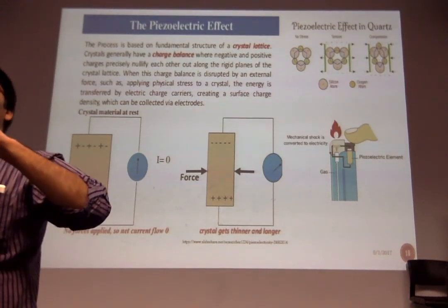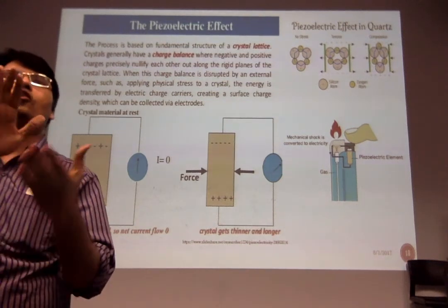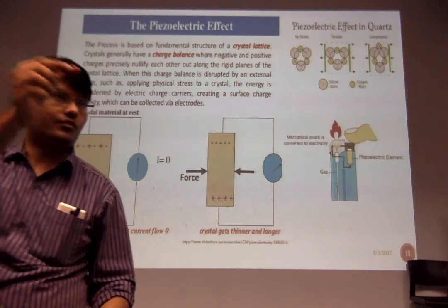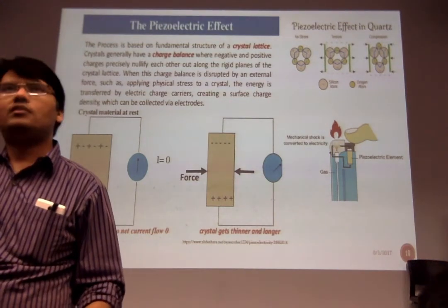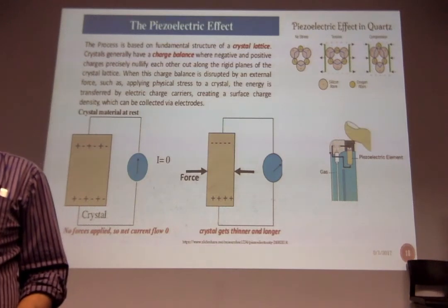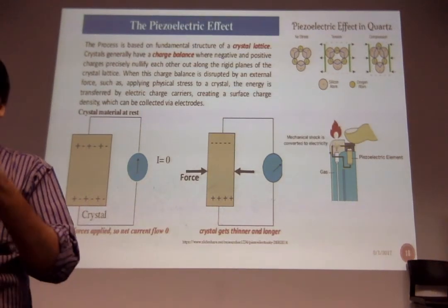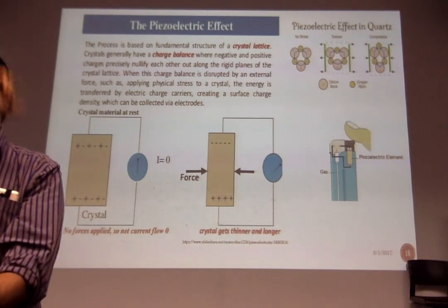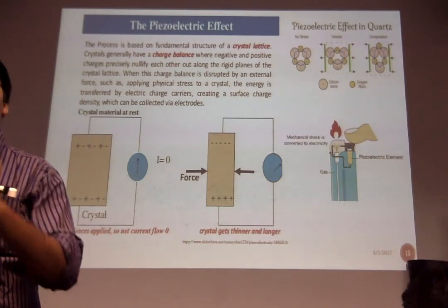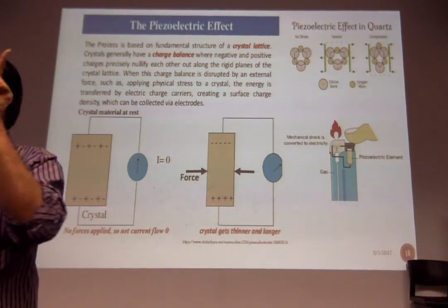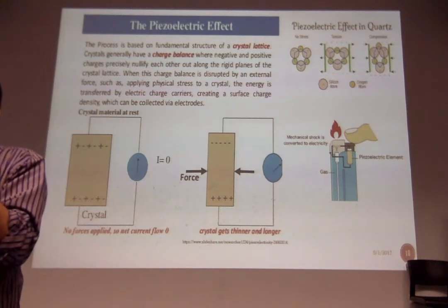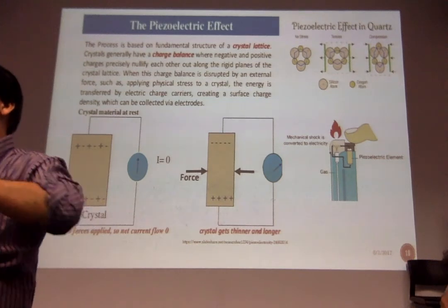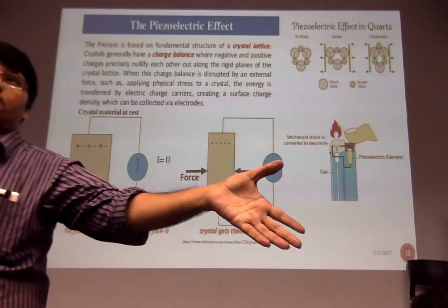That's why this has been extremely well used as a crystal oscillator in all our circuits. If you see your Altera boards, you see 50 megahertz; that is the crystal. That's actually a quartz crystal inside. That quartz crystal was cut in such a way that its mechanical resonant frequency was 50 megahertz. So it vibrates, it shakes at 50 megahertz. That means every 20 nanoseconds it's shaking, is it? So it's producing that sinusoidal signal for us and it is running our microprocessors.